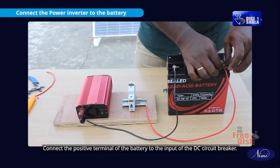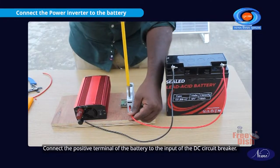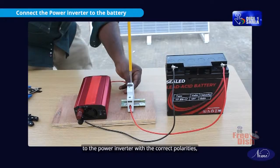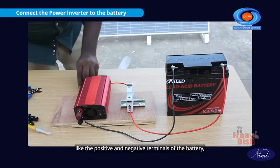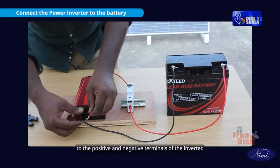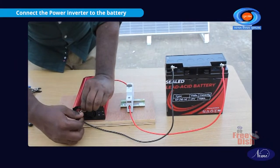Connect the positive terminal of the battery to the input of the DC circuit breaker. Connect the output side of the DC circuit breaker to the power inverter with the correct polarities, like the positive and negative terminals of the battery to the positive and negative terminals of the inverter.